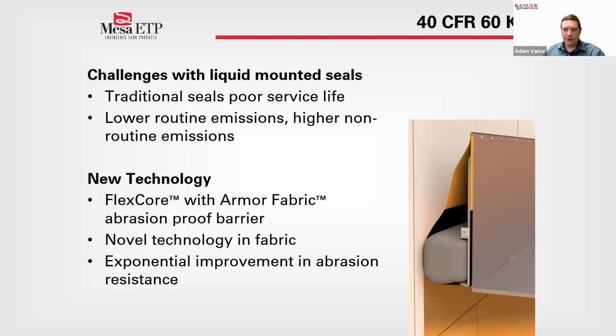This liquid mounted seal addresses durability concerns with some novel technology in fabric that is chemically resistant, but also exponentially more abrasion resistant than urethane. Our analysis and tests showed the longevity of this technology achieves mechanical shoe reliability or even longer. So the regulations around emissions control, as we see them, are likely to become more stringent over the years, and we as an industry need to keep identifying those trends in a search for new technology to support the industry and the environment.